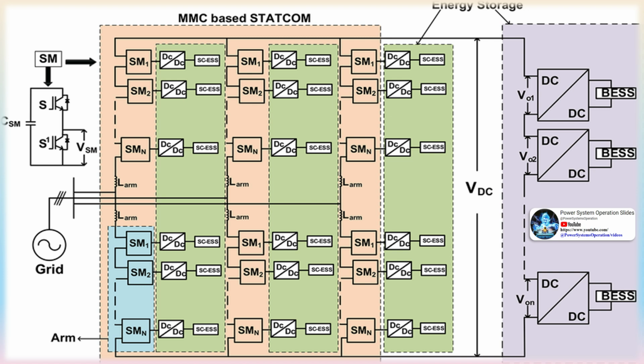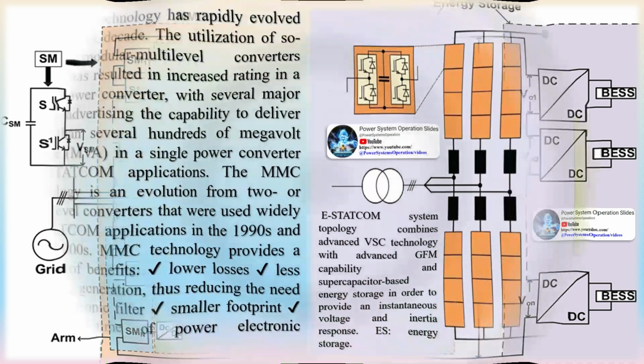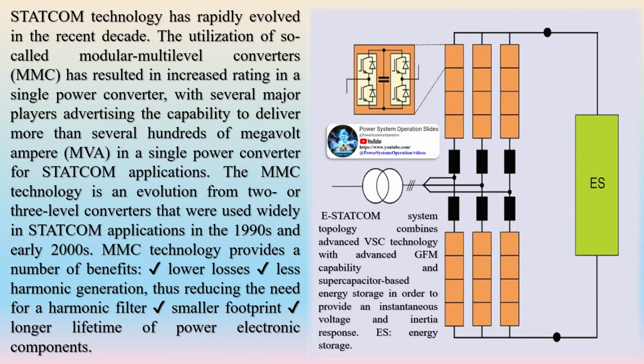Power system deregulation, along with transmission limitations and generation shortages, has altered grid conditions, creating scenarios where energy storage technology plays a crucial role in maintaining system reliability and power quality. Energy storage devices offer multiple benefits, such as rapidly damping oscillations, responding to sudden load transients, and continuing to supply power during transmission or distribution interruptions. Additionally, these systems can correct load voltage profiles through rapid reactive power control, allowing generators to balance with the system load at their normal speed.